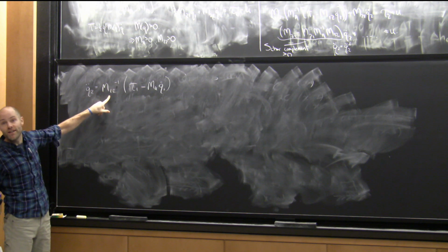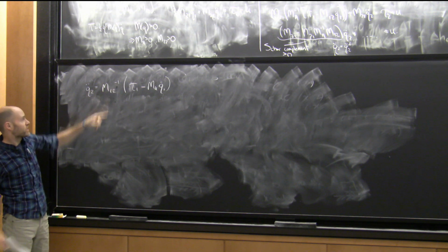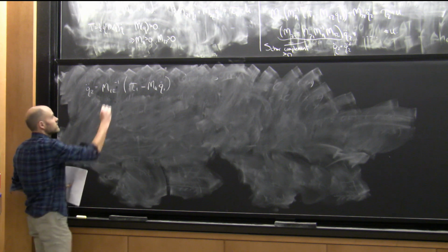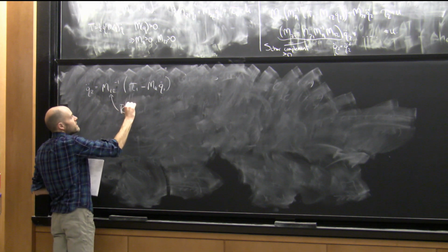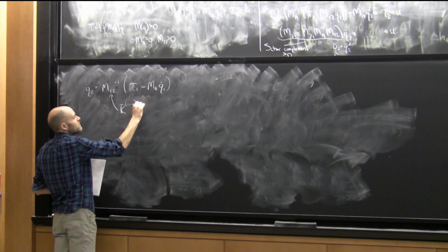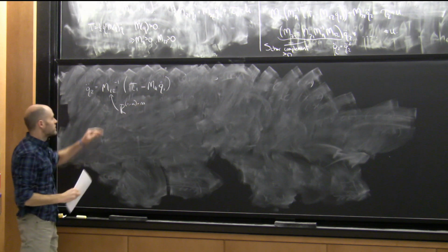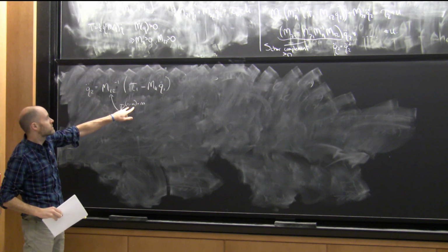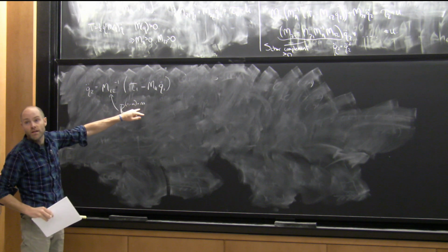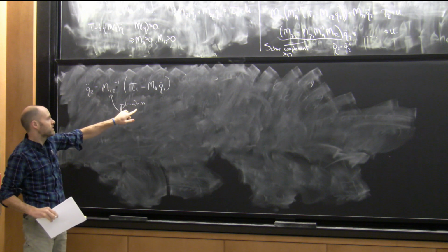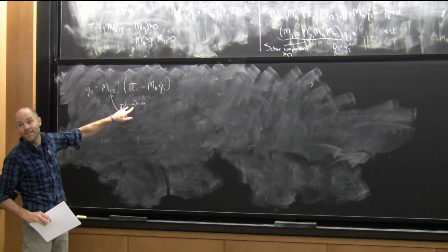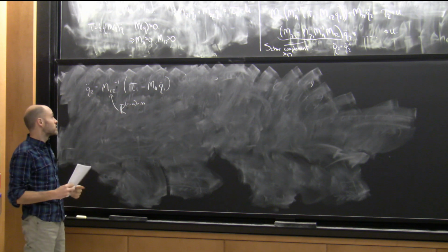What's the size of this matrix, right? This thing lives in R^((n-m)×m), right? It's the number of passive joints by the number of actuators. Okay, so this could be very small, and there's no chance of that being invertible.